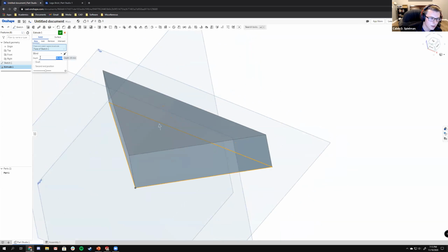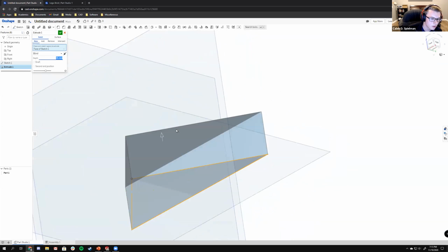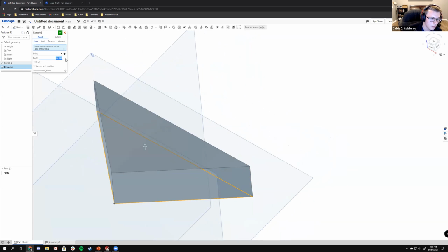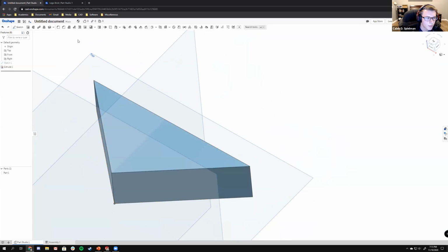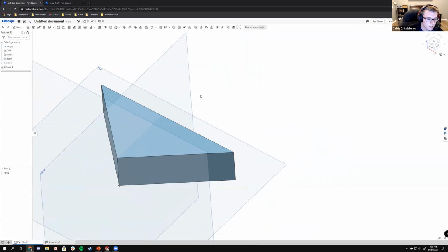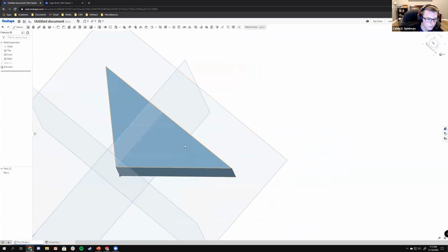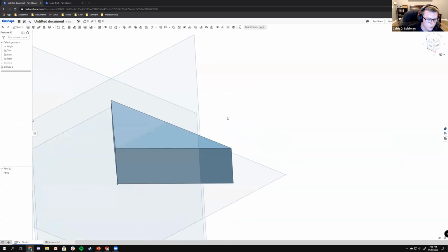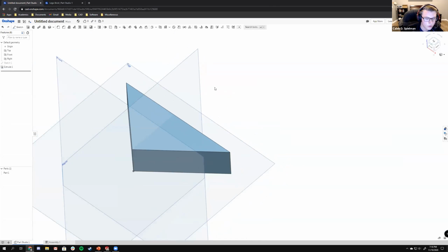Then it selects, this time it selected a contour automatically. So let's just select it again, and we can define it as a blind extrusion just in a specific direction, defined by a magnitude, in this case, 25 millimeters. And we can click check on that. For Onshape, if you ever press the red X, all of your work is gone, never to be seen again. And yeah, so the extrusion tools between Onshape and SolidWorks are very similar.